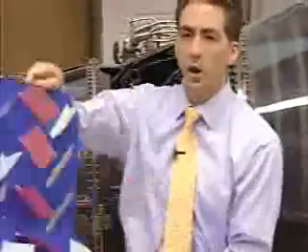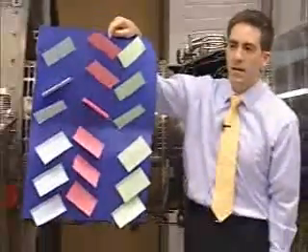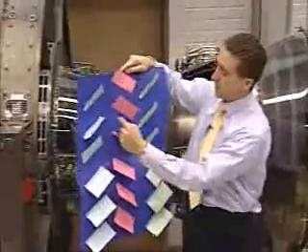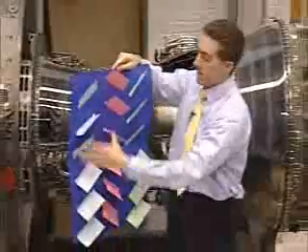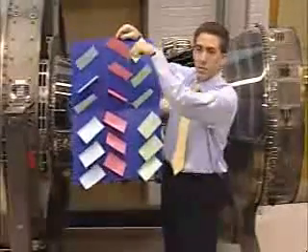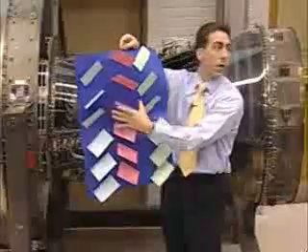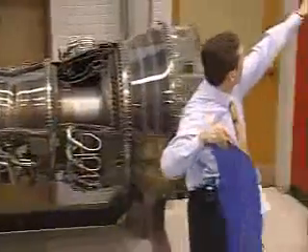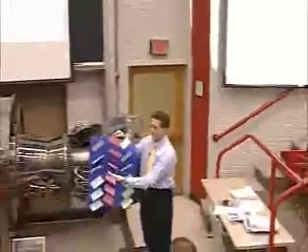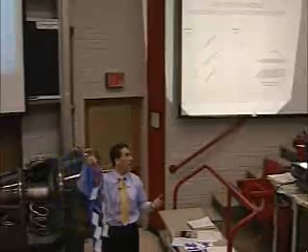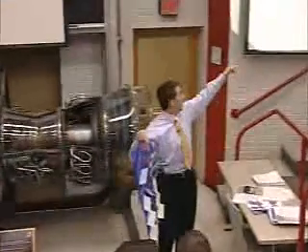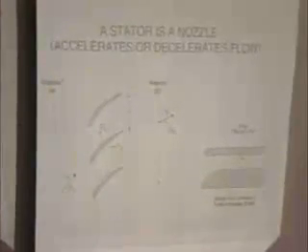Now I'm going to cut it and open it up. And now what I have is a bunch of blades that go from 0 to 2 pi, or an infinite row that's just stationary, and then an infinite row that's moving down or up. Right? This is the moving part. Right? Now, look at that picture. Each one of those blades at an angle in an infinite row is just a blade row. And that's what it means to unwrap a compressor. And we'll solve the problem in this sort of frame. Are there questions about that?